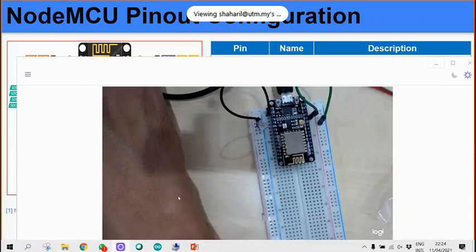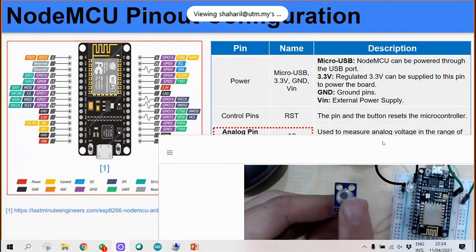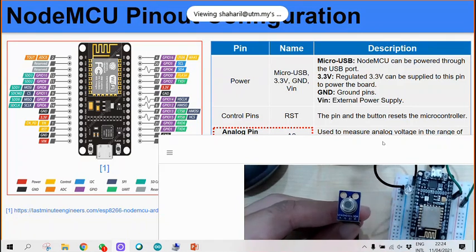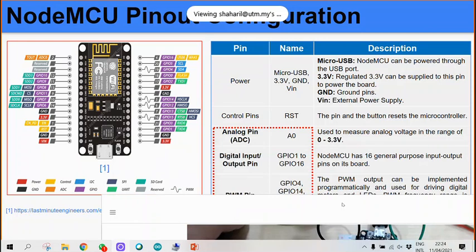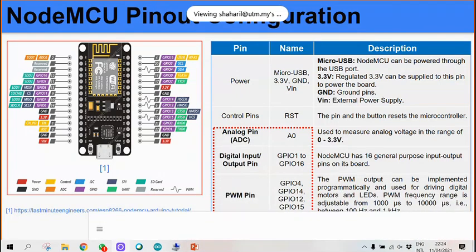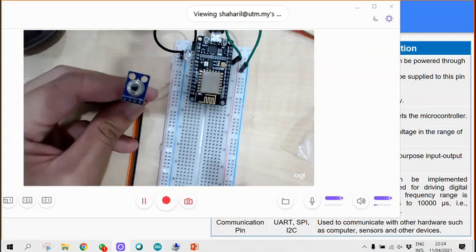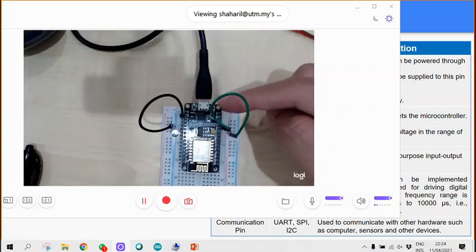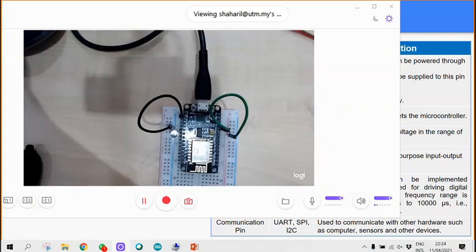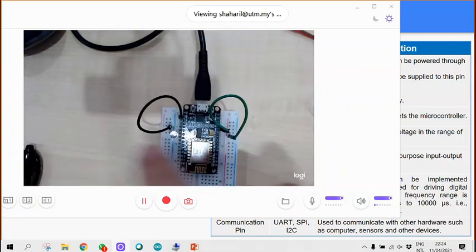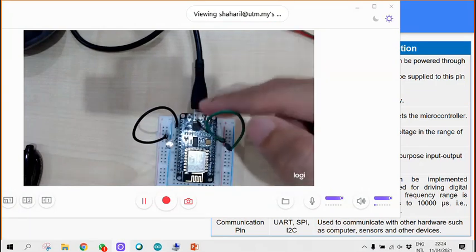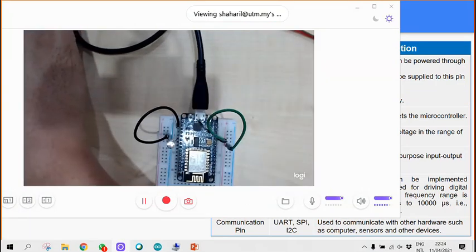Let me explain it to you. This is your sensor. You want the MCU to talk with this. One of the options is to use the protocol we call I2C. And if you want your MCU to talk to your PC, your computer, it uses the UART protocol.